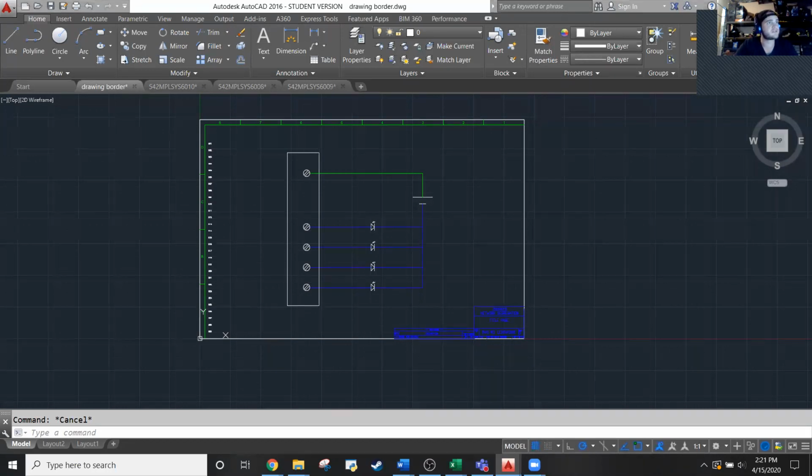Matthew has a comment here. Got it to work. Just turn on off every setting in the layer properties and regenerate the layout. Yeah, that's kind of like rebooting your computer. Who knows what the problem was, but that'll definitely fix it.